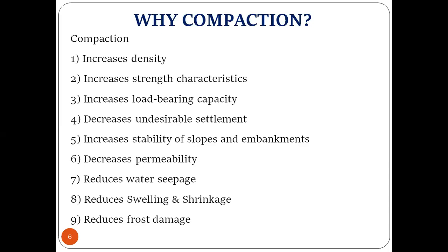Same thing here, water: if water expels out, the soil swells or shrinks, right? So here it is a denser soil, fully packed, so there will be no swelling and shrinkage problem. It also reduces frost damage. There are no voids to be filled by ice, right? The ice will not fill into the voids, so there will be no frost damage also.